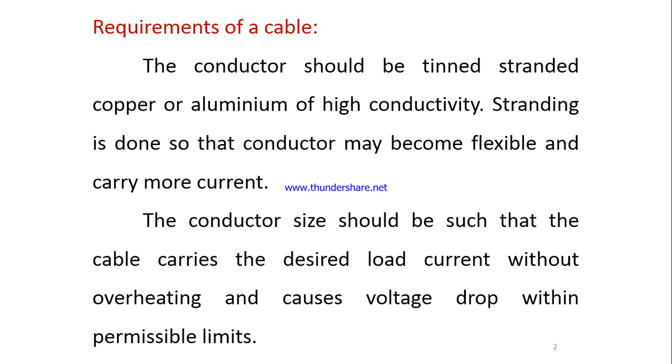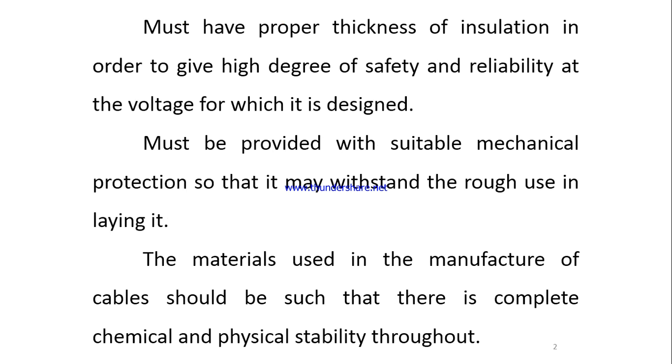The requirement of the cable is that the core conductor has to be made up of stranded copper or aluminium, which has high conductivity, and the conductor size should be such that it is capable of carrying the desired load current without any overheating or voltage drop. The thickness of insulation should be appropriate to ensure the degree of safety and reliability. Then mechanical protection has to be sufficiently provided in order to maintain the physical stability and chemical stability of the materials.